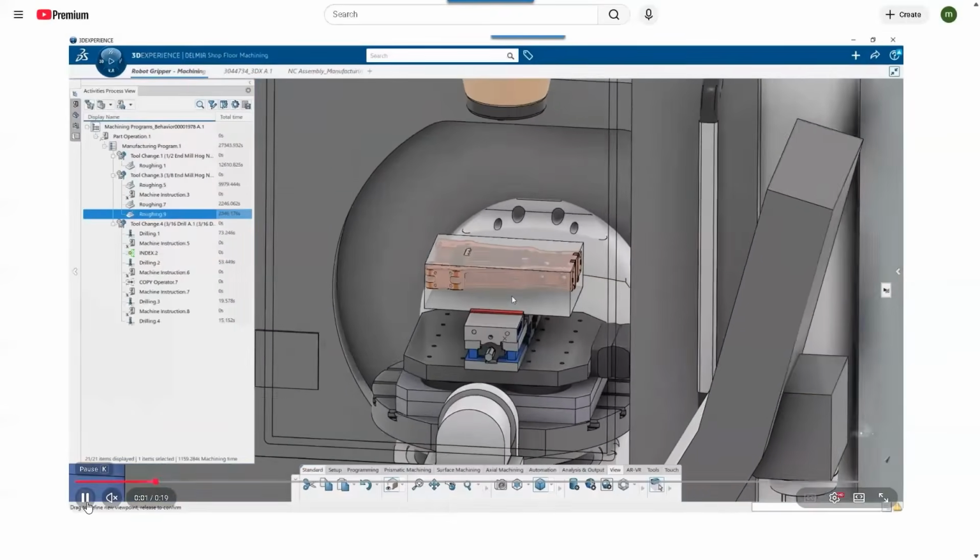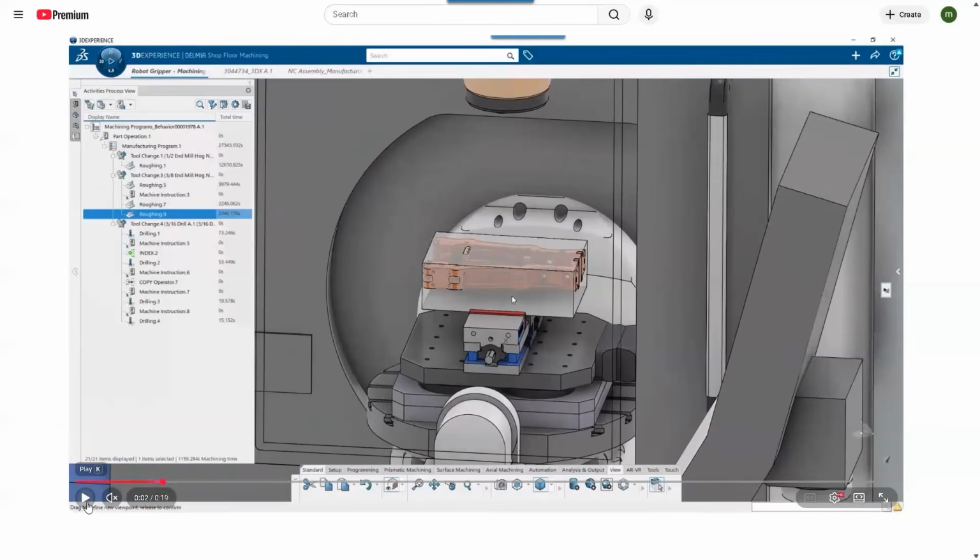Another benefit that happens with our advanced machining is any of our platform capability has machine simulation set into it. So if we have the model of the machine set up for you with the kinematics and the movement and the jaws and the vise and all that good stuff, you're working and programming within the environment of that machine. So as I look at this, I have this DN machine here. I have a rotary table, I have a vise. And then as I program this, I'm just programming the part and the software is solving that simulation for me.